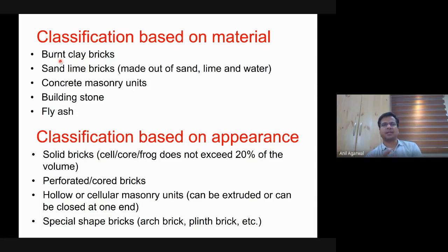Then you may have some sand lime bricks, which are not as commonly used nowadays, but in certain areas where lime is abundantly available, these bricks could be used. Lime also has some adhesive properties like cement. So once you mix it with water and then the water dries up, it hardens, it develops a significant amount of strength. So these don't have to be burnt, they can have sufficient strength. Okay.